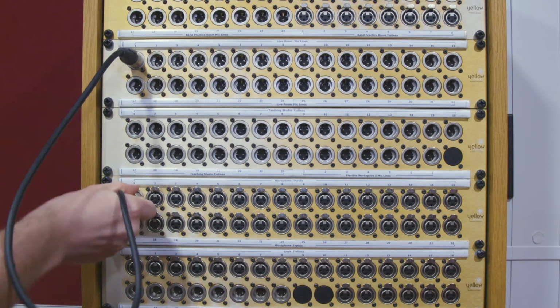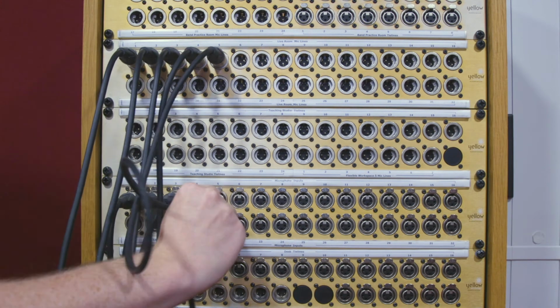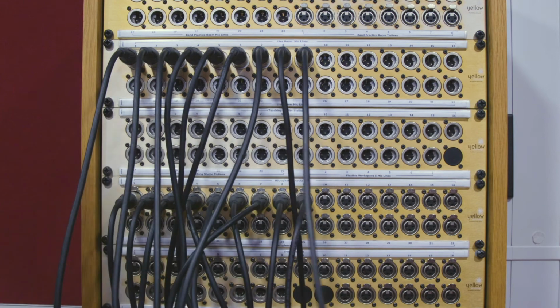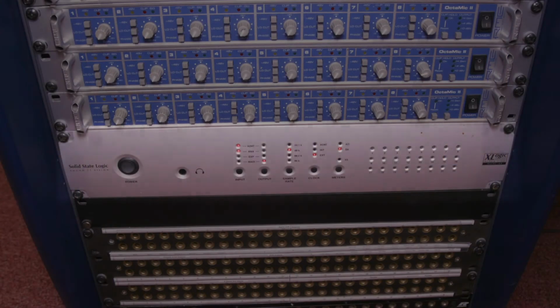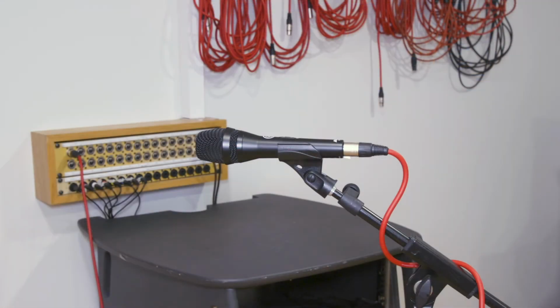This means that input channel 1 on the live room patch bay connects to channel 1 on the control room patch bay and channel 1 on the main microphone preamps. We'll talk about the preamps more in a moment. After being amplified, the signal flows into the external sound card, which is operated through Pro Tools running on the PC. Thinking about this signal flow will help you to troubleshoot issues you're having with your recording.